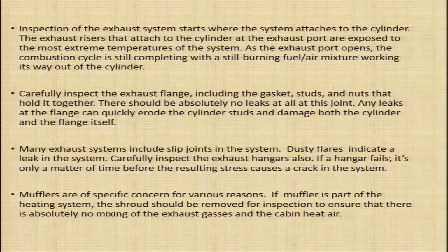Inspection of the exhaust system starts where the system attaches to the cylinder. So, when the exhaust system is connected to the cylinder exhaust port, the inspection starts right from that point. The exhaust risers that attach to the cylinder at the exhaust port are exposed to the most extreme temperatures of the system. So, these exhaust risers are exposed to the most extreme temperatures of the engine because the exhaust gases come directly from the exhaust port into these areas.